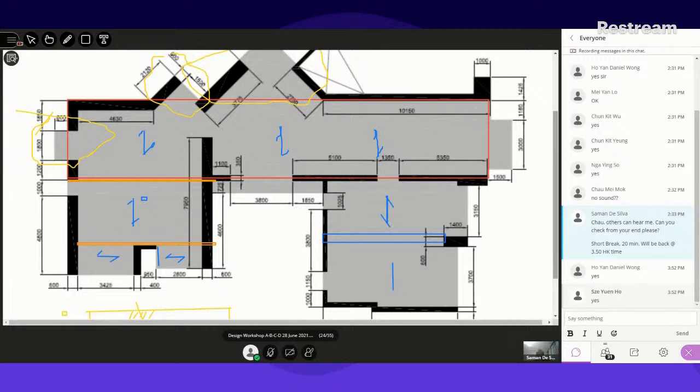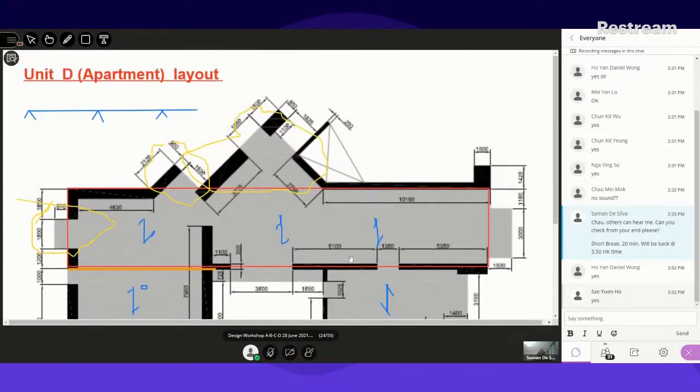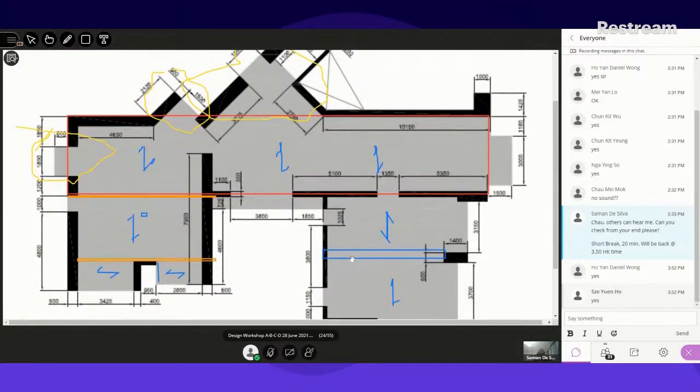I also have this one nicely going that way. So you need a beam here, of course. This is 5 meters, this is nearly 3 meters, but there's 1,400 in D here, which means that this will be about 9 meters or less. So you need a beam here, a beam here and a beam here, and then the rest will come into play.